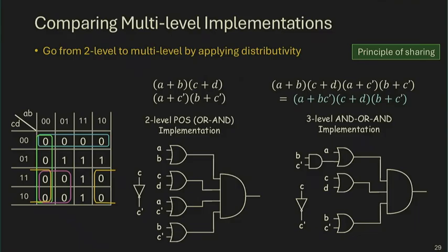All right, so we have just done several implementations based on the SOP expression. You can also implement any circuit using a product of sums form, right? An OR gate followed by an AND gate. And between SOP and POS, there's also no clear winner. Either one could be the better implementation. You really have to try both to figure out which one is better.